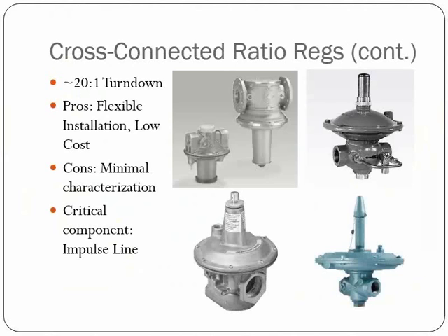So you've got different locations to put these in and install these in. The downside of the ratio regulators is that there is minimal characterization. I think there is an adjustment point on most of the ratio regulators, and of course you have your limiting orifice. So essentially you have 2 points of adjustment. So typically, like I mentioned before, you would set up